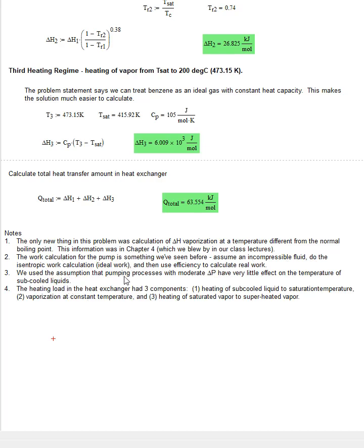We also used the assumption that a pumping process with a moderate change in pressure has very little effect on the temperature of subcooled liquids. So that let us say that T2 is equal to T1.